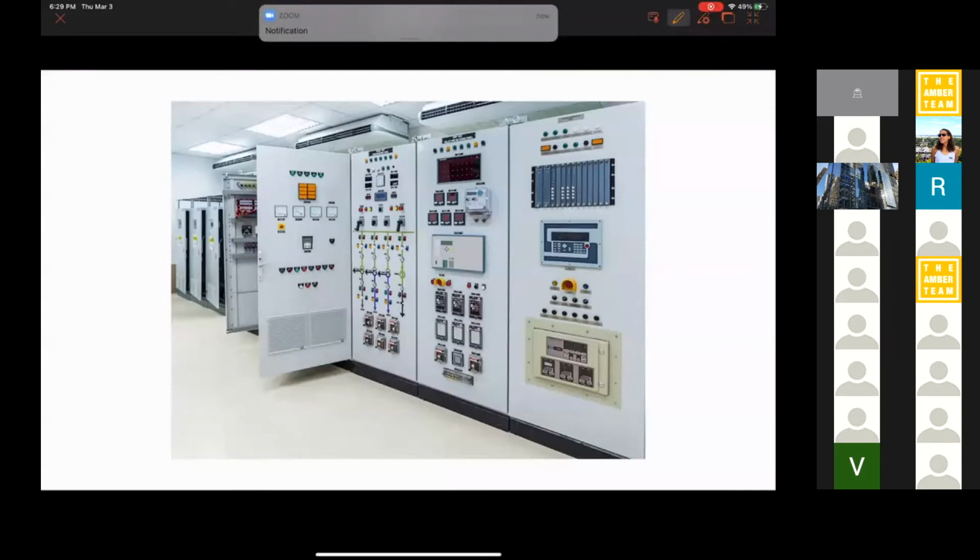And they're anywhere between the area of a football field and a quarter of a football field, something like that. That's where you're stepping down the voltage to go into the neighborhood. So that's when we're going from 100,000 volts to 10,000 volts. That's when we're going from the erector set voltage to the regular tree telephone pole voltage.